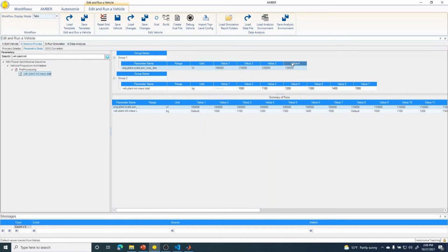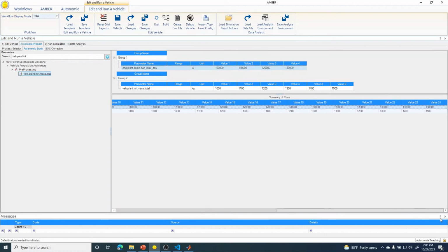And you'll see that it'll do 4. I have the default value since I appended it. It's appending it, so we'll remove the first value. So we'll have 4 by 6 or 24 values. So if we go out, you'll see the 24 values, and you can see the values it'll sweep in the table. So if you ran it this way, you would have 24 simulation runs.